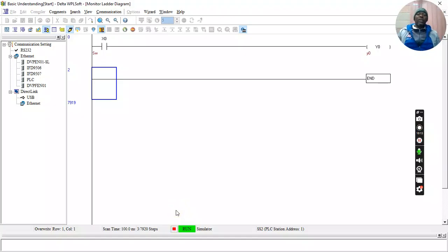All right. So now because it's on run mode, I can then test my PLC. Now what I'll do is I come to the contact of my switch. I activate it. How would this work in real life? In real life, I would have had to actually energize the input X1, right? If I energize the input X1 with a proper input, remember some inputs can be 115 volts, some inputs can be DC 24 volts, some inputs can be 230 volts. So you have to check what your input voltages are supposed to be, right? And some of them are already pre-wired for you as digital inputs. All you have to do is close and open switches, right?